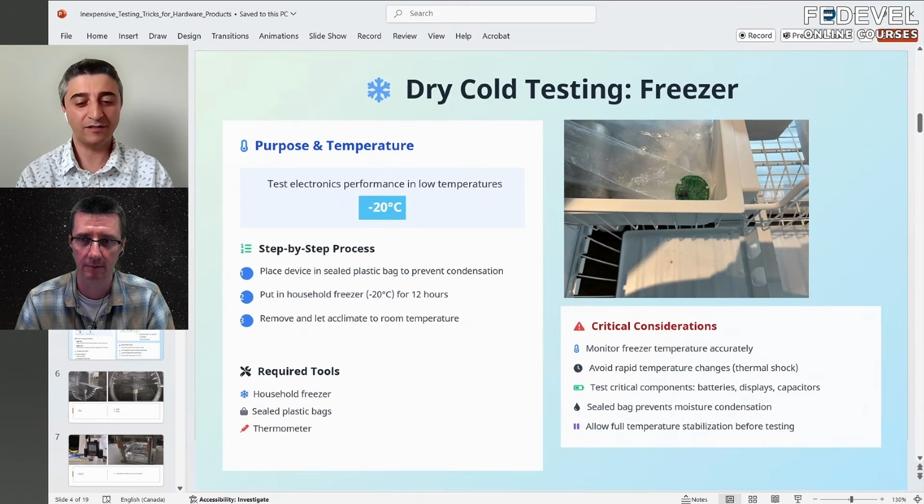Of course, not all enclosures are like this, but this is for an average one. Wires: you'll be surprised, if you use a solid wire that is 24 gauge and it's really cold, you might snap it off and it might break easily. That's why using stranded wires might be a better approach for these kinds of applications. And like you said, it's easy.